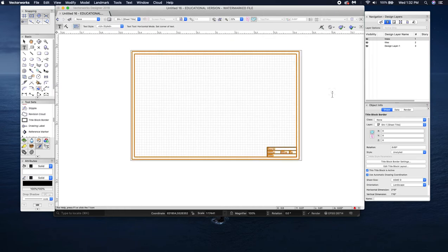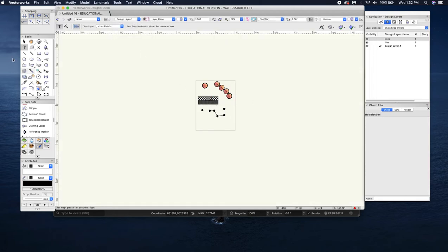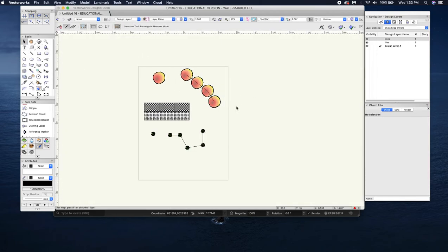Next thing that we need to do is to create viewports. Viewports are the things that are gonna be imported into your printout page, sort of like a frame of the different objects that you want to bring in. So I'm gonna give you an example to make it a little clear. So we're gonna go back into our design layer. To do that, we click on the arrow here, and we're gonna go design layer 1. Okay, so now I'm back onto my page.